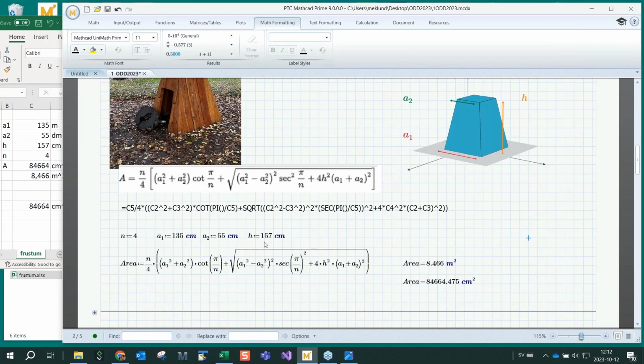Let's say I've got help from someone else who's more familiar with inches and feet and things like that, then maybe that person would say that the height was 5 feet, and that's not a problem. We can mix length units. Everything is converted internally into meters anyway, so no problem. And even saying, okay, I want the result in feet squared.